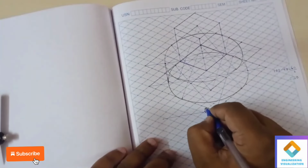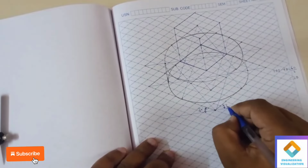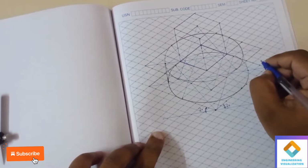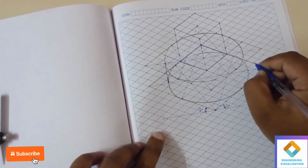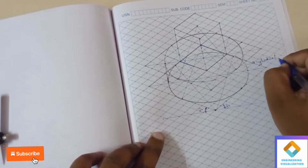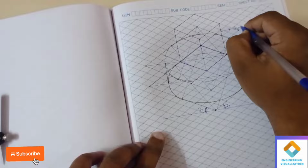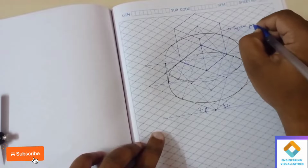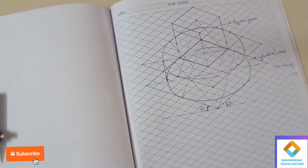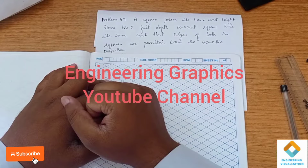So I can mention the angle 30 degree for the base where we have taken a reference. You can see this is our cylindrical slab, dimension 100 into 100 and height 30. This is a square prism, dimension base side 40, height 50 mm. So that completes the problem. Problem number 49 from the CAD solution book in the isometric.